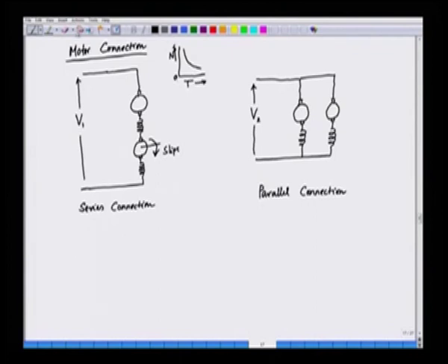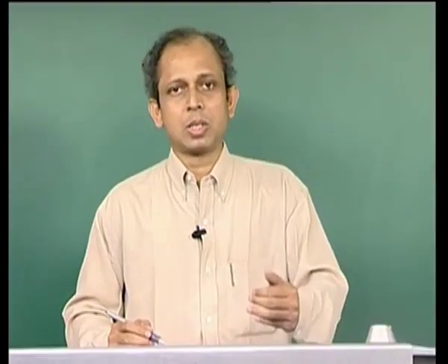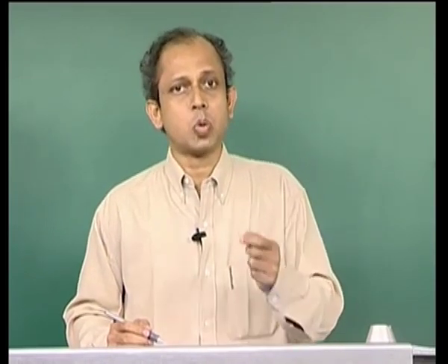This is the torque we have in its axis. So, if the speed increases, torque will reduce, and if the torque reduces, the current through this series combination will also reduce. So, when the motor slips, the speed increases, the current will come down, and the torque will reduce. The torque is going to reduce in both the motors, because both the motors are series connected. And hence, when the wheel slips, there will be a net reduction in the torque.